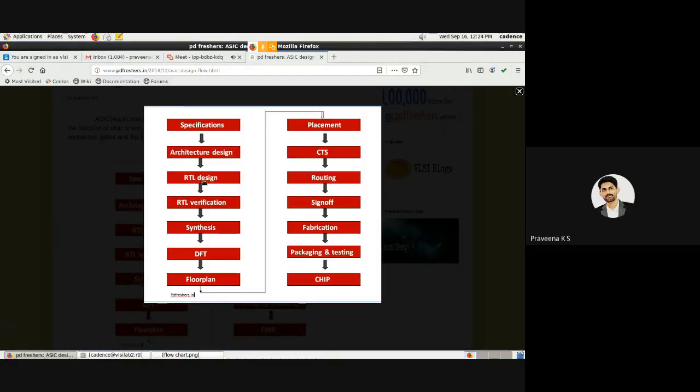I have written the RTL design code, but to verify the code I have to write its test bench code also, by writing its input and output sequence. For an AND gate you have 4 combinations: 0 0, 0 1, 1 0, and 1 1. You have to give its test bench for simulation purposes. You can write it afterwards, or at the same time for verification.